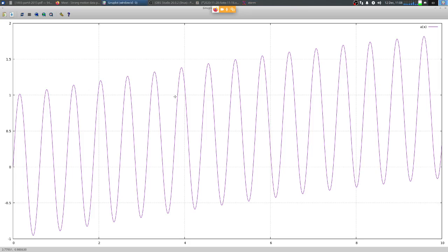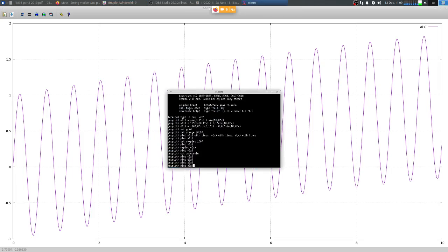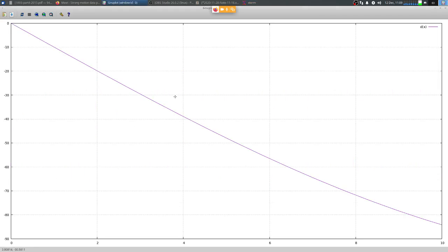Acceleration is dominated by high frequencies. Low frequencies only provide the baseline about which the high frequencies oscillate. But in the displacement, it is the lower frequency which governs. High frequencies do not appear at all, they are unrecognizable.